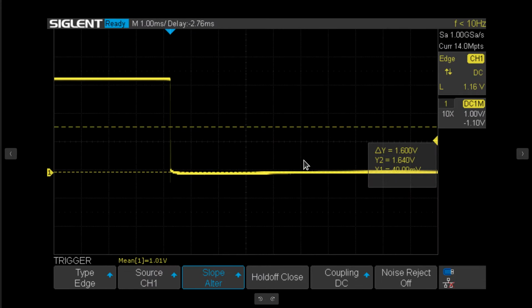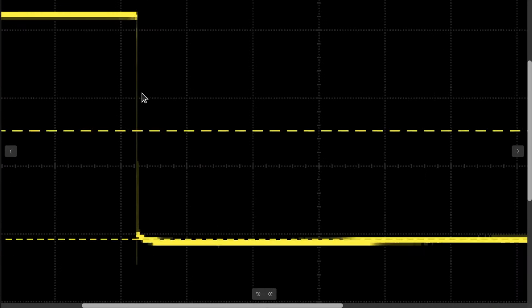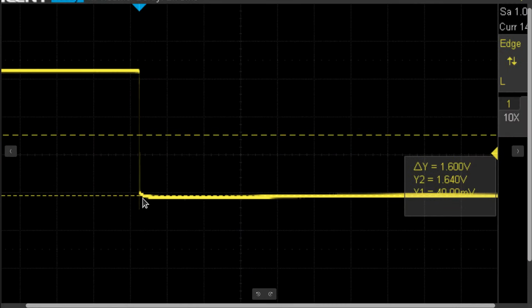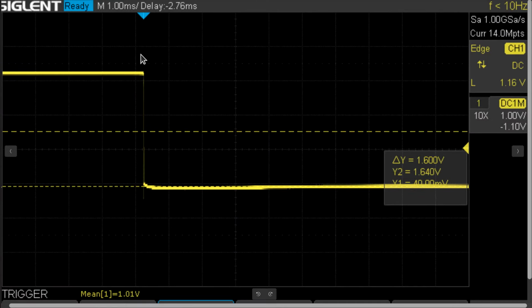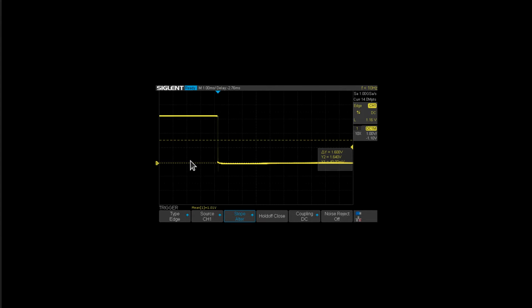This is your best scenario. One of the times I pressed it, it was really clean. If you look in here really close, though, it might have a little bit of a whipsaw in there. What is the signal on a 1 millisecond scale? This one is nice. It'd be nice if all switches were this great. Then we just simply set it to 1 millisecond, which in this case is an enormous amount of time, but not too bad for human finger speed, right?